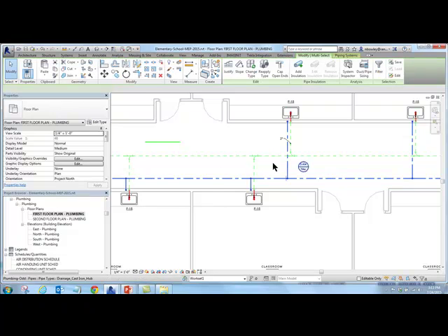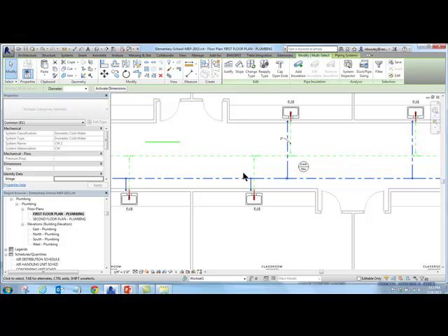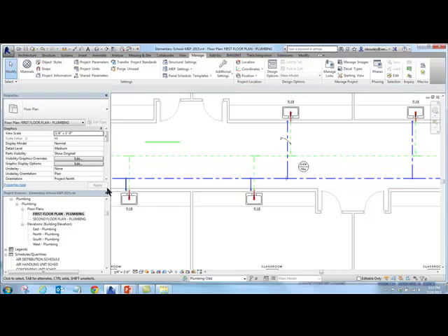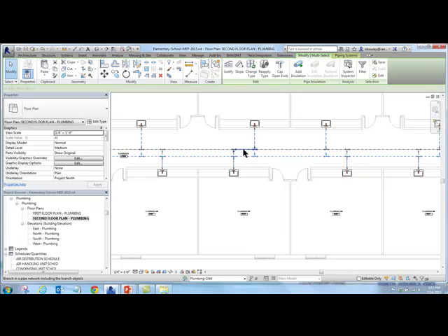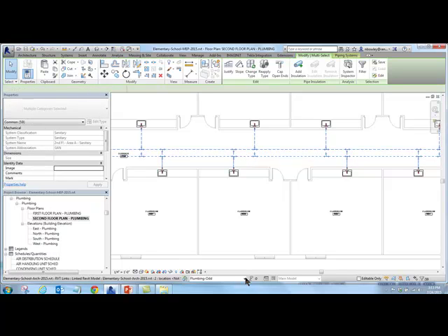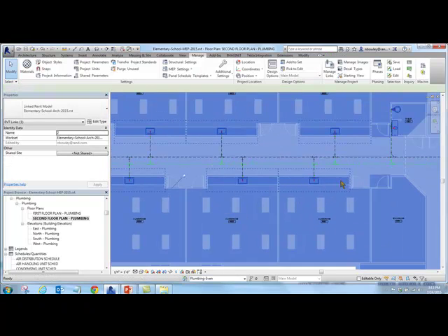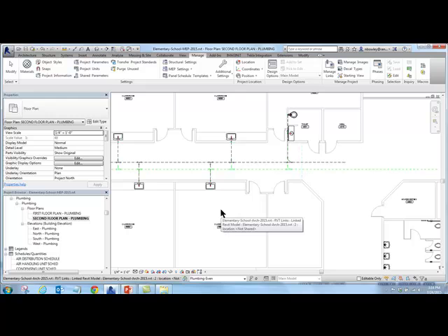is take all of the piping on, say, the first floor, third floor, whatever, and you put it on the odd workset. And again, I'm glad I never had to do this, but if you're insisting on doing this, this is how you can do it. You put it on an odd workset, and if it's in an even floor plan, such as this sanitary here, and this vent even, you put that on an even workset. If it's a riser that goes to the floor, you put that on the common workset.